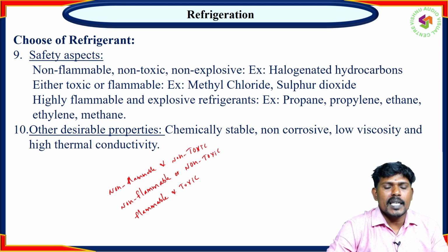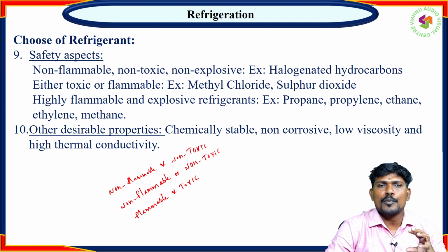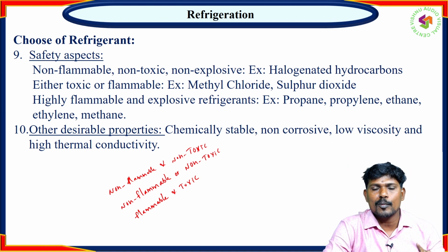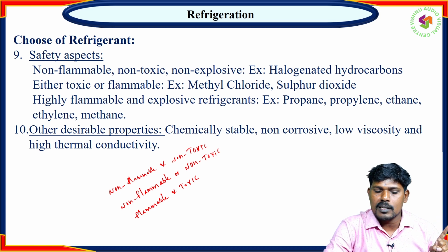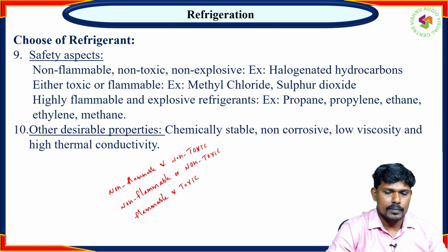Next one, other desirable properties. Because the refrigerant will stay in the refrigeration process for a long duration, the refrigerant must be chemically stable, non-corrosive, low viscosity, and high thermal conductivity. So these are preferable.